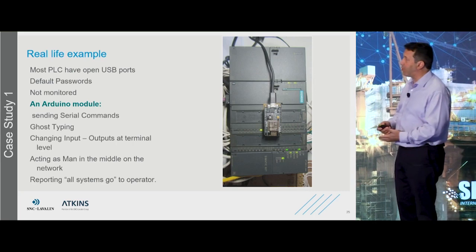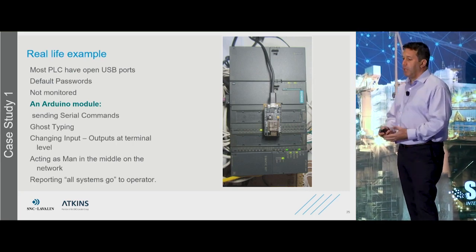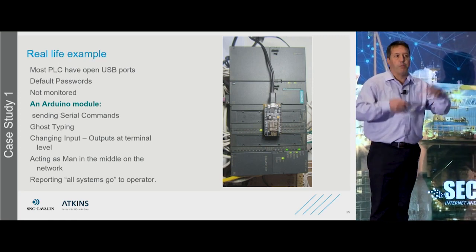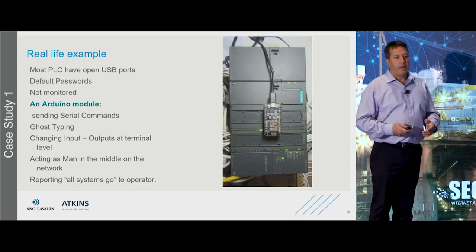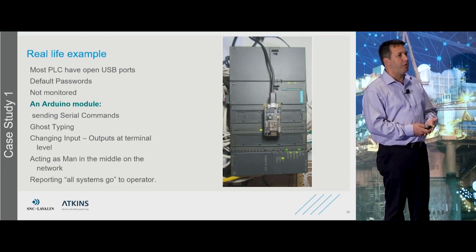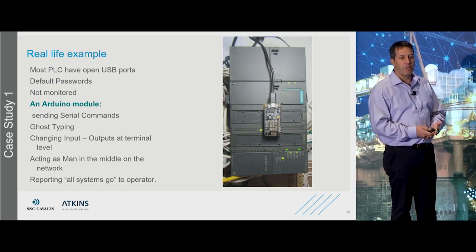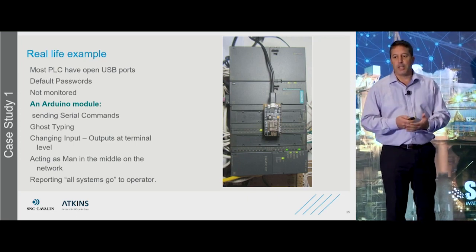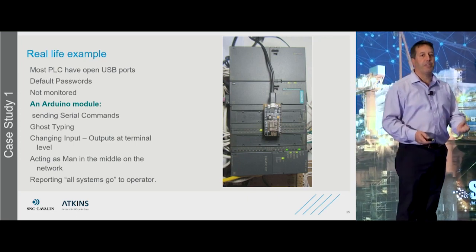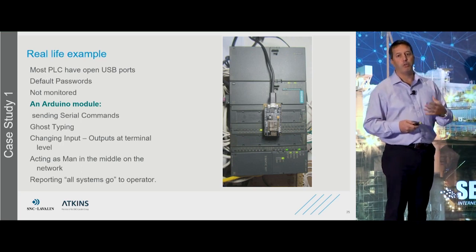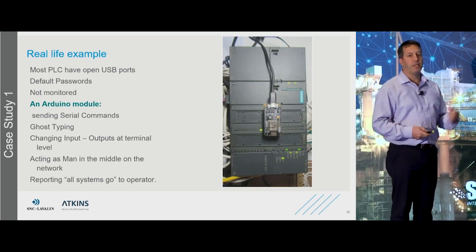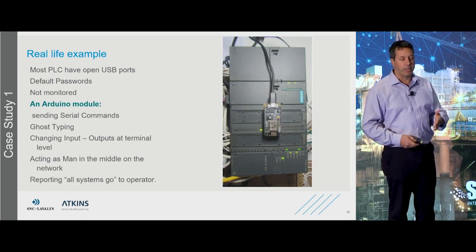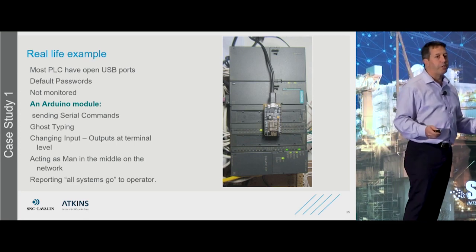So most PLCs have open USB ports, and you say, yeah, but when you plug a thumb drive in there, the system will detect it. We have systems that will detect that. Well, guess what? When you plug a new keyboard into your computer, does it tell you that you've plugged in a new keyboard? No, because the OS is made to not necessarily detect that. It will take in the input from a keyboard, but will not tell the user or any other system that a new keyboard has been plugged in. So for any PLC with a USB port, if you plug a keyboard into it, you could, and most PLCs still have default passwords, believe it or not. We see that all the time.